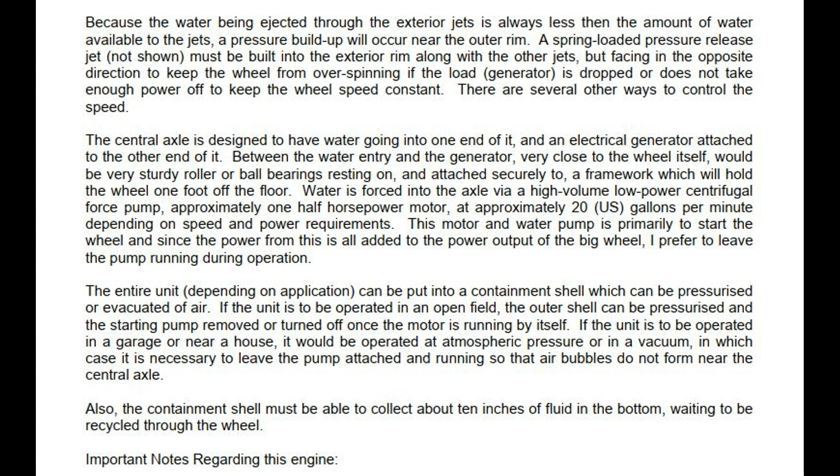Water is forced into the axle via a high-volume low-power centrifugal force pump, approximately 1/2 horsepower motor, at approximately 20 US gallons per minute depending on speed and power requirements. This motor and water pump is primarily to start the wheel, and since the power from this is all added to the power output of the big wheel, I prefer to leave the pump running during operation.